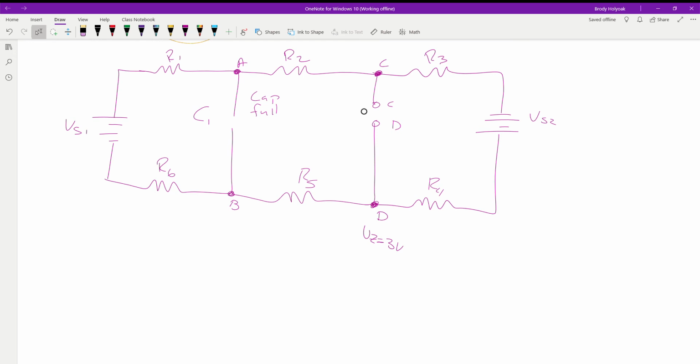So you have to check to see if it's forward or reverse, and then you have to see, does the voltage that's available to it match my Zener diode? If it does, great. If it doesn't, it's a little more interesting because you're going to have more voltage dropped. So let's say when we go through this, we find our Zener diode is reverse biased, which is the way it should operate.